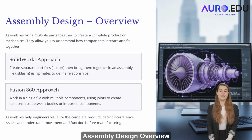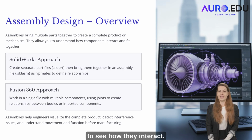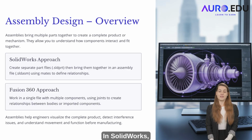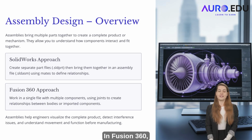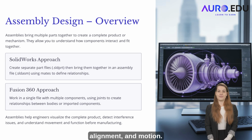8. Assembly design. Overview. Assemblies let you bring multiple parts together to see how they interact. Each part is a separate body, and you can position them inside an assembly file. In SolidWorks, you create assemblies in a new document. In Fusion 360, you can build them in the same file. Assemblies help you understand fitment, alignment, and motion.